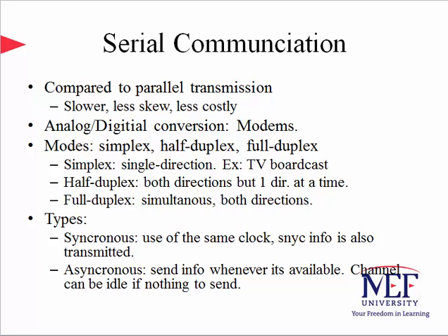There are two types of communications: synchronous or asynchronous. Synchronous communication uses the same clock and it needs to be synced, so sometimes synchronization information needs to be sent for this purpose, and it's sent along with the data to the destination. Asynchronous communication, on the other hand, sends information whenever it's available. So the channel can stay idle for long periods of time if there is nothing to send. So as you can observe, the channel might not be very well utilized in that case.